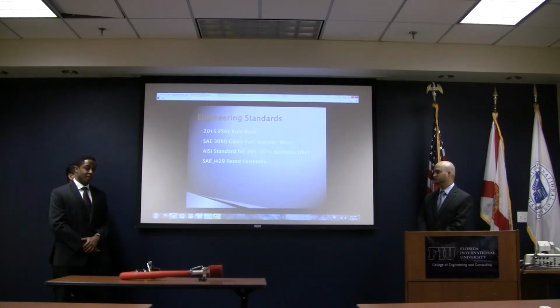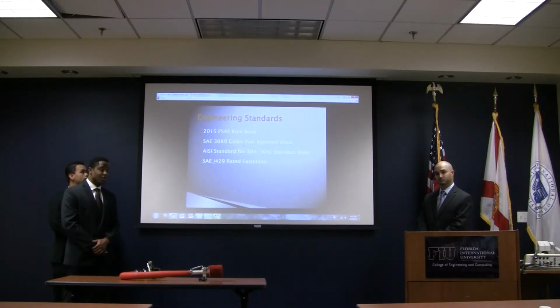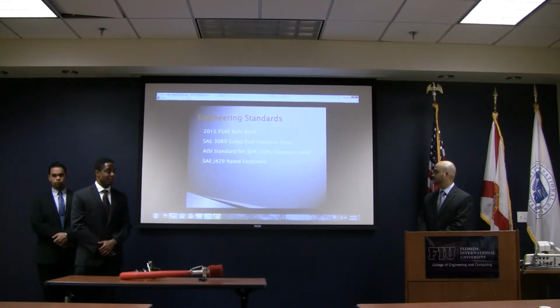With respect to engineering standards, we were guided mostly by the Formula SAE rulebook, but with that being said, we utilized SAE 30R9 Gates fuel injection hose. We also used AISI standards for our 304 and 304L stainless steels, and we used SAE J429 rated fasteners.